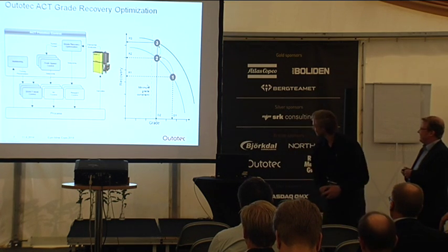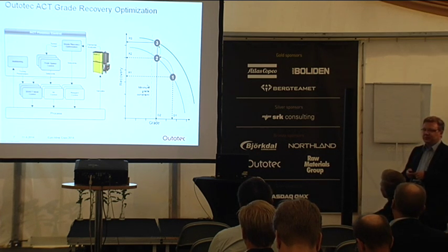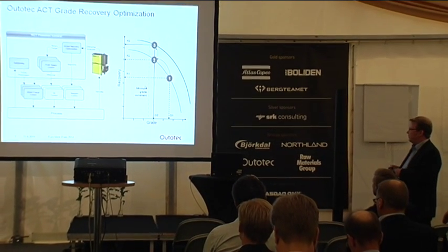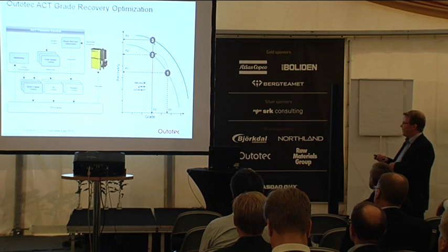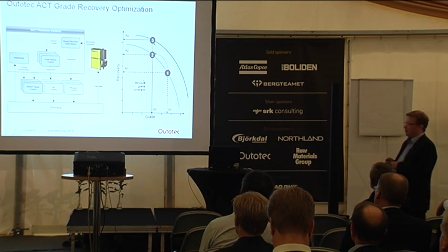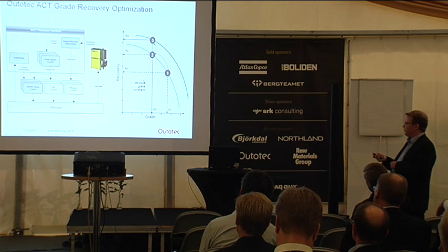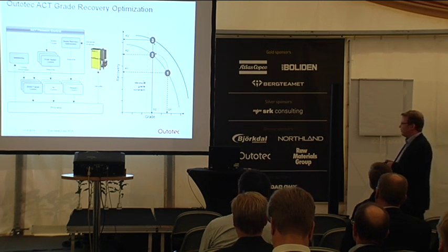All right. Then our grade recovery optimization on the flotation side, a little bit similar in principle to the grinding, is based on the standard modules implemented in our ACT expert control software. There are stabilizing components for the froth velocity control using froth cameras, the FrothSense system there, and optimization utilizes the elemental assays of the Courier analyzer. When optimization is applied, the set points are applied to the froth velocity set points and also the reagent addition. This is a very typical way to structure optimizing of the flotation circuits.